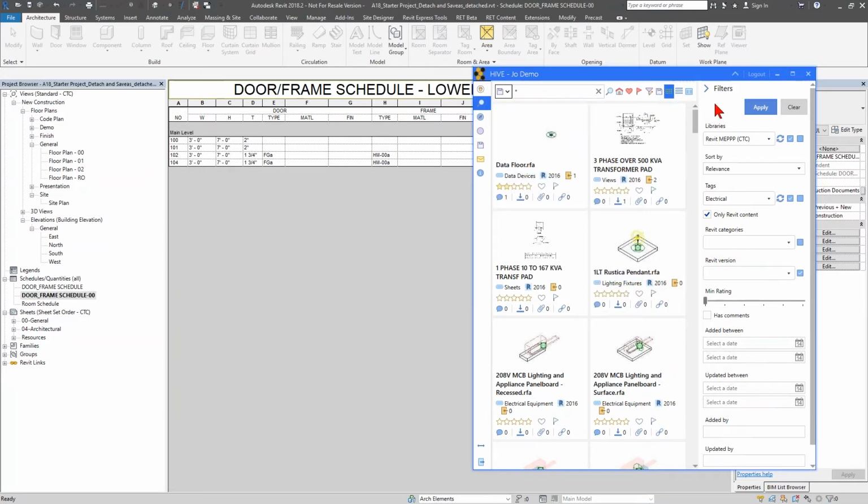So at this point, from this point forward throughout the day, I could potentially collapse filters and just run searches here at the top, and it will always look in a certain library for anything that contains the electrical tags. I'm only going to get returned back electrical specific content. That's it. Or if I wanted to have, say, an architectural search, I could do something similar. Maybe I want to look at my main corporate library over here for my main set of content, and I don't want to search electrical, I want to search architecture. So from this point forward, I will never get back anything that is not tagged architecture. It's, again, only giving me Revit content. I could also specifically say, only give me back certain versions of Revit, only give me my current Revit 2018 version.